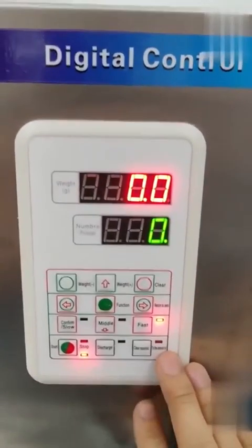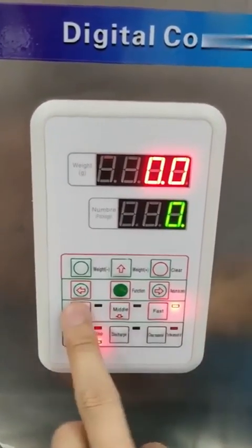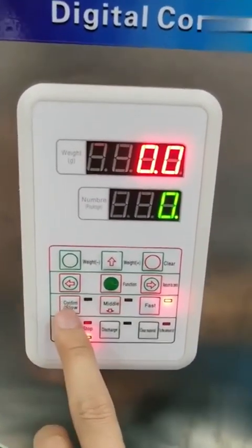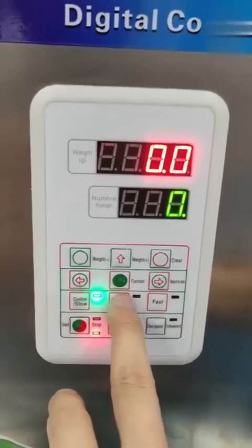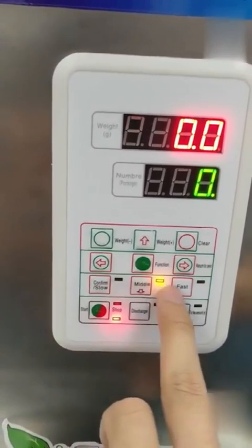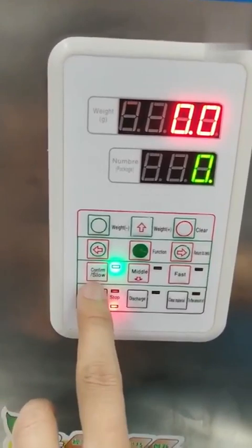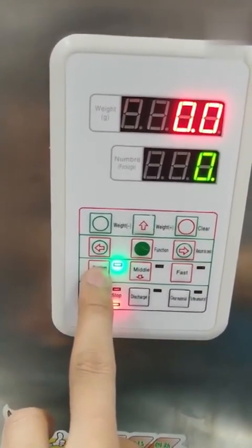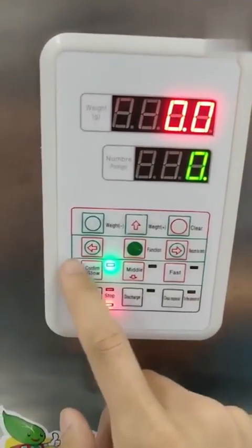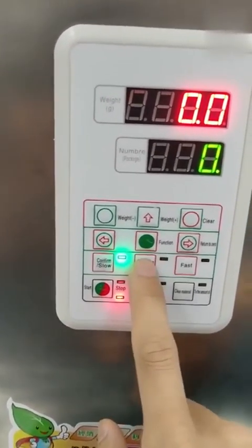So here I'm going to show you how to do it on the control panel. You can see these are 3 different speed settings that were pre-stored on the machine. If we are going to mess with the speed setting, first we're going to choose one of the speeds, because the settings will override the original default settings. So right now I'm choosing the slow speed. When I enter the setting and save, the speed will be saved on this button. Okay, so same for the other 2.